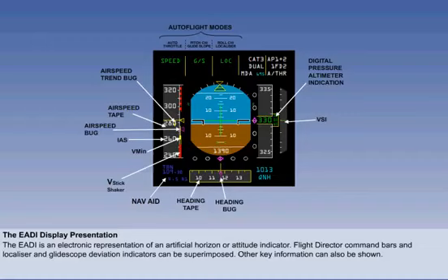In this particular display, which is representative of the primary flight display on an Airbus A300, radio altitude is incorporated in the location shown here. Note, however, that the layout of screen displays can vary slightly between manufacturers, although the information displayed will be essentially the same. Often the radio altitude display, which also incorporates a decision height alert, is located at the bottom right of the screen.